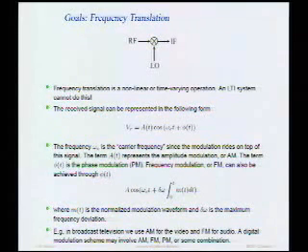And as I already mentioned, a linear time invariant system cannot perform frequency translation. So what is frequency translation? That means that you have an input at one frequency and an output that's at a different frequency. One way to build a device that frequency translates is to use a nonlinearity, and we'll be looking at that in this course. Another way to do it is to use a time-varying circuit. Both approaches are valid ways of building mixers. Mixers are circuits that perform this frequency translation.